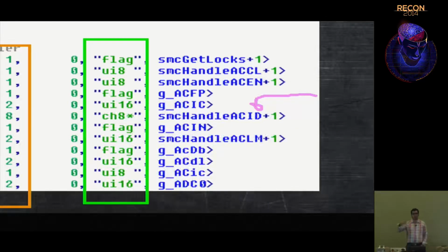And that's actually some ARM assembly code that's going to run, talk across the I2C bus where my AC charger is plugged in, and figure out what the AC charger's identification bytes are, and then determine if this is an authentic Apple charger or not an authentic Apple charger, and warn you that the charger is not supported.